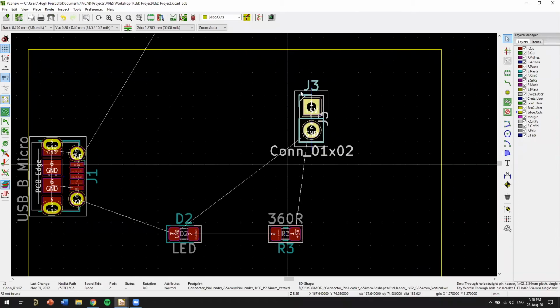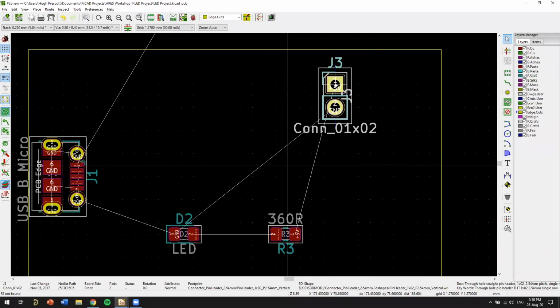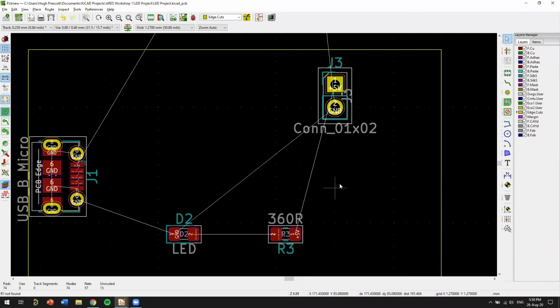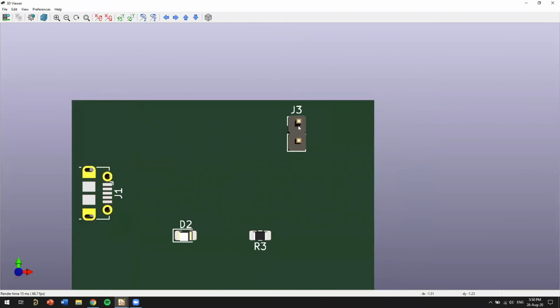Just because they're on different 5-volt lines. But that's good because then we can see how you update the PCB later. So here, we want to put 5 volts here and ground here, and then run our power through this system and then back to ground.